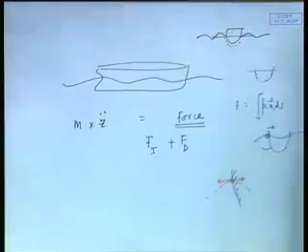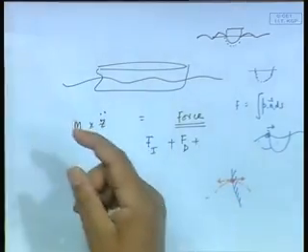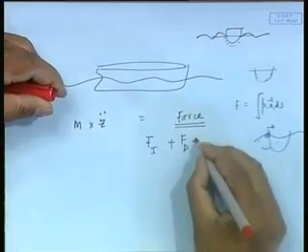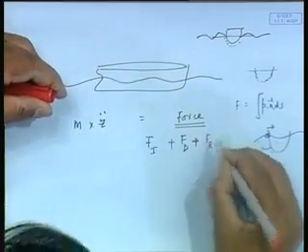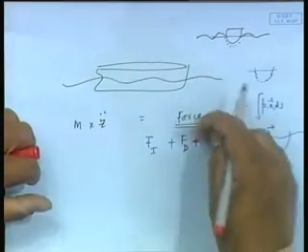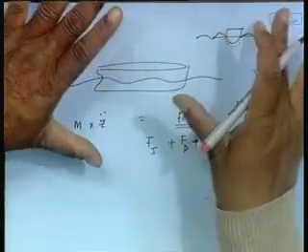So obviously there is a pressure field introduced. That is one more kind of waves that comes in. This is known as radiated waves, or radiation waves, or another wave, let me call it FR. When I say FR, please understand, it implies all effects connected to the wave system created by oscillation of the hull in otherwise calm water. So I end up getting this.